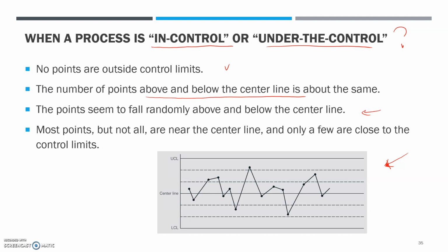So here, not many are staying outside of the second standard deviation distance. Only this one is staying outside of the second standard deviation. It is closer to the upper control limit. All other points are actually embracing this central line. There's no traceable pattern, and nothing too close or too far from the central line. And this is what we would expect by just looking at it.